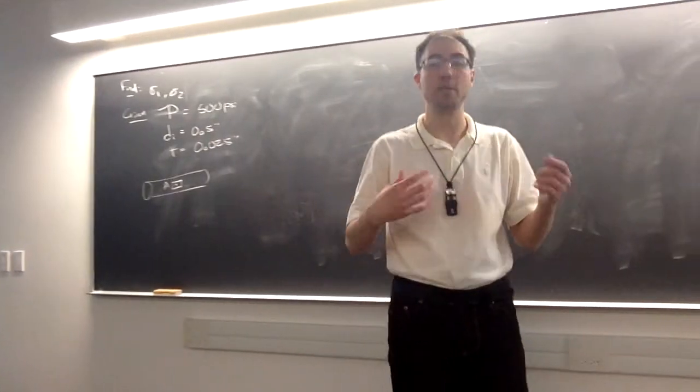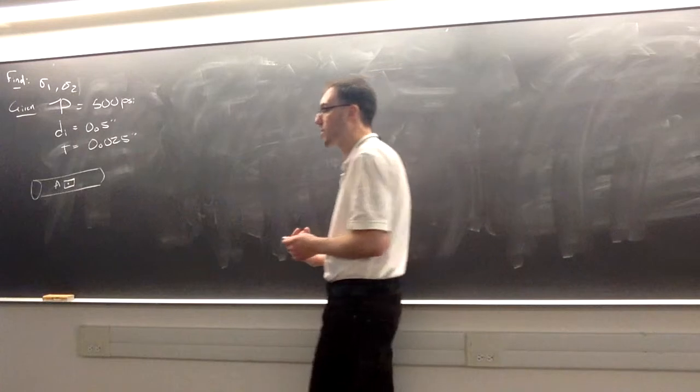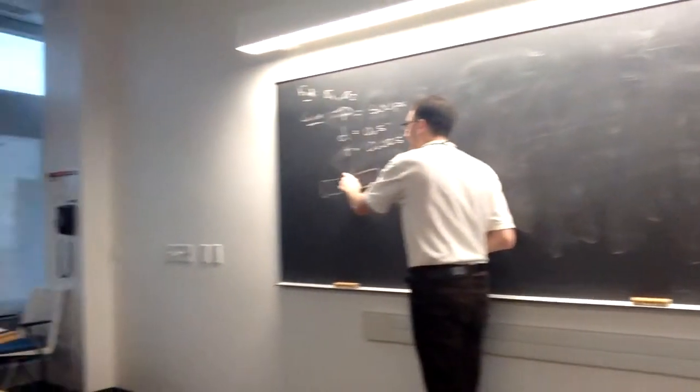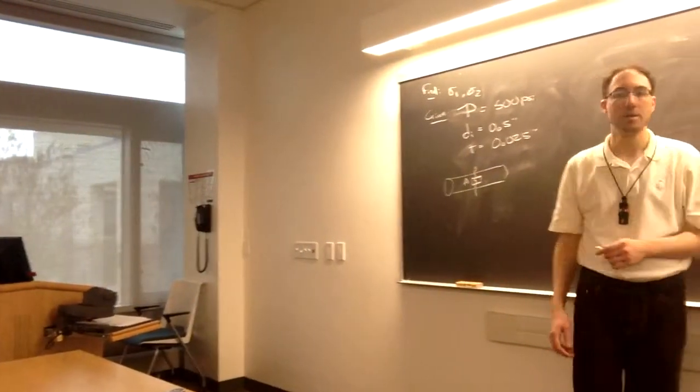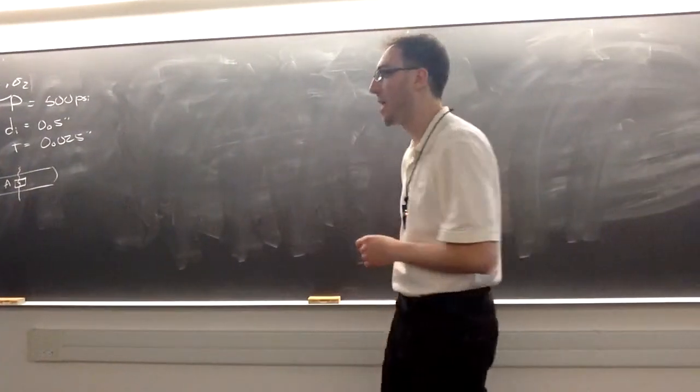In order to find the principal stresses, we need an initial stress state. To find the initial stress state, we're going to need to make a cut through that element so that we can see what the loads are and therefore what the stresses are acting on our element.